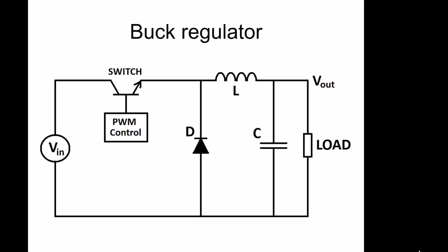This is a schematic of a buck regulator. You have your input voltage, you have a switch, so this is an electronic switch controlled by a signal, and then you have components, the main part being this inductor here.